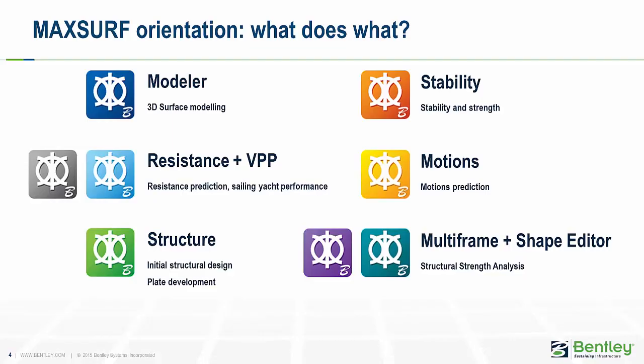Motions is used to estimate the vessel motions in waves. Strip theory for heave and pitch motions of slender ship forms operating with forward speed, and a zero-speed radiation diffraction method which can be applied to a greater variety of marine vehicles and computes all 6 degrees of freedom. Both are inviscid potential methods, and viscous damping is taken into account with coefficients provided by the user. It can also compute performance metrics such as acceleration, motion sickness incidence, etc.